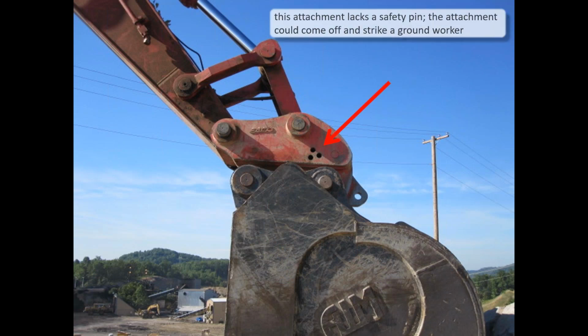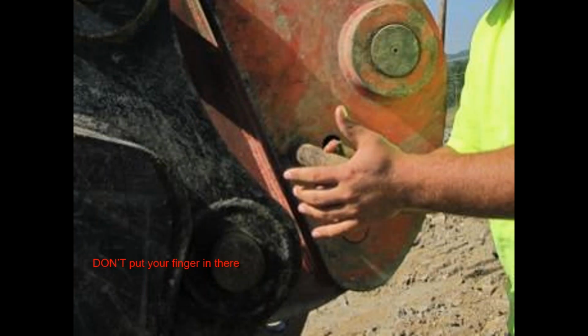Attachments. This one, they're lacking the safety pin or a keeper to hold the attachment in place. They've got it hooked up, but there's actually supposed to be a safety pin that you have to remove in order to detach it. They can technically, inside the cab, take the attachment off, but you've got to have the safety pins.